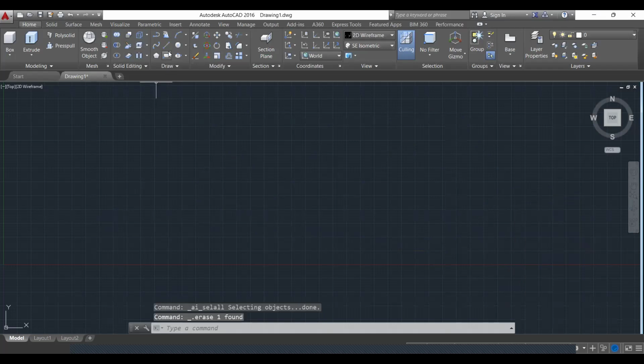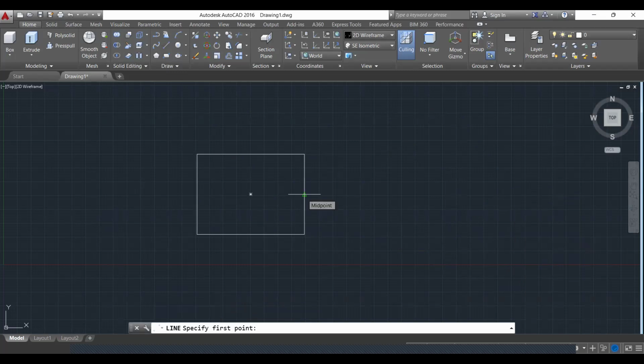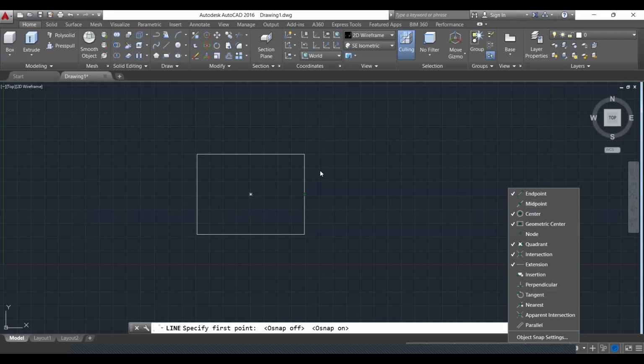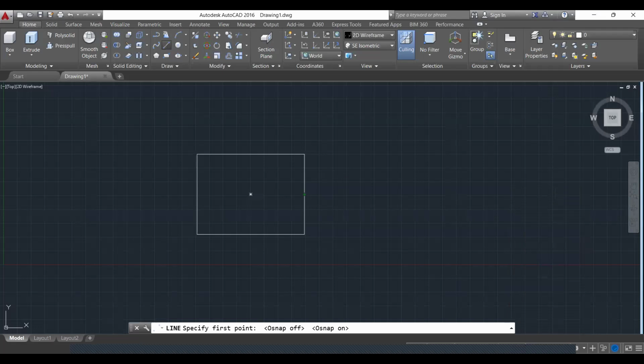So with the help of the midpoint, when I draw something like this, you see there is a center to everything. And assuming I pick another line that I'm about to draw, the moment I bring it here, the software automatically directs me to where I want to point. You see, it gives some form of locking to that space. Assuming this midpoint is not turned on, I wouldn't get the center. You see, the center is not coming, which means maybe I have to calculate and know the center.